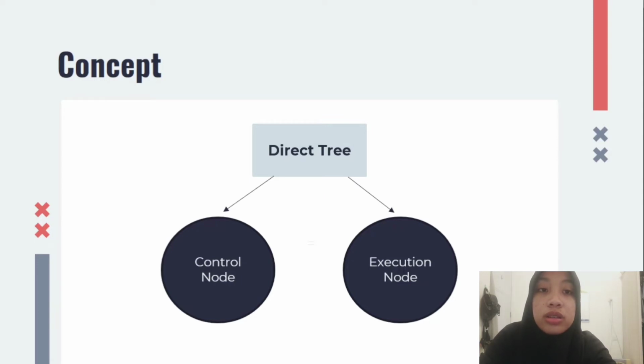And the control nodes are internal nodes and define how to traverse the BT given the status of their children. Importantly, children of control nodes can be execution nodes or control nodes themselves. Sequence, fallbacks, and parallel nodes can have any number of children, but differ in how they process children. Decorator nodes necessarily have one child and modify its behavior with some custom-defined policy.